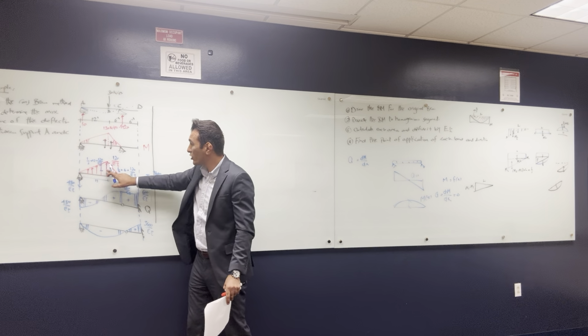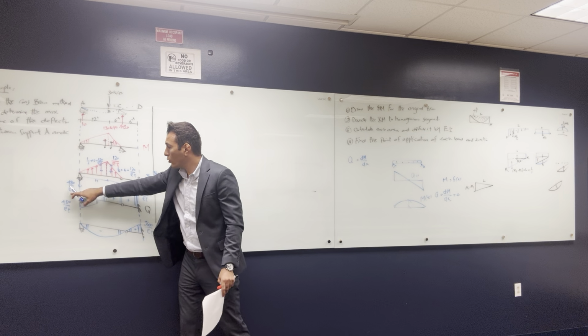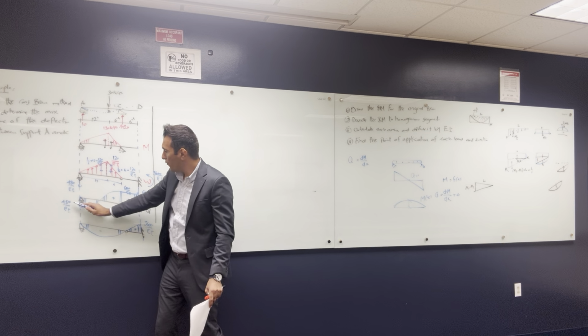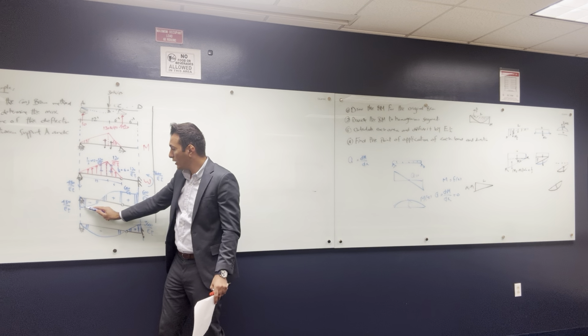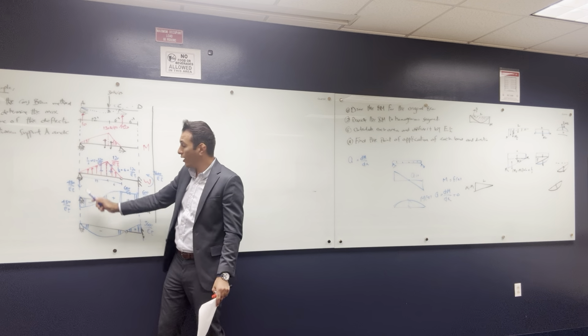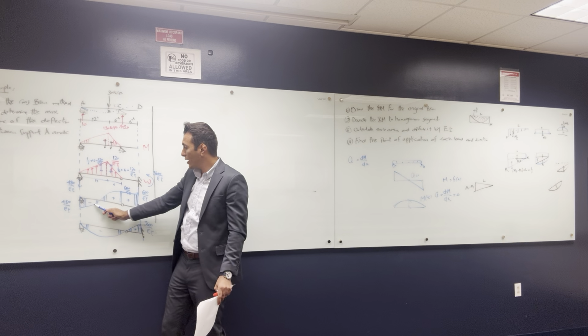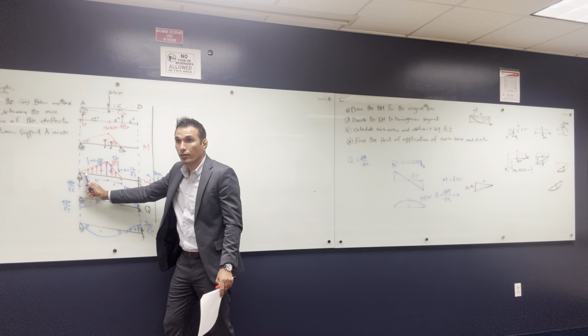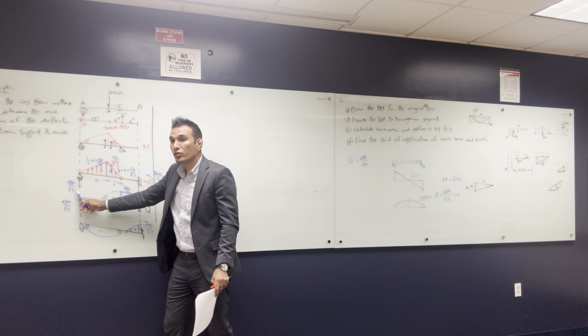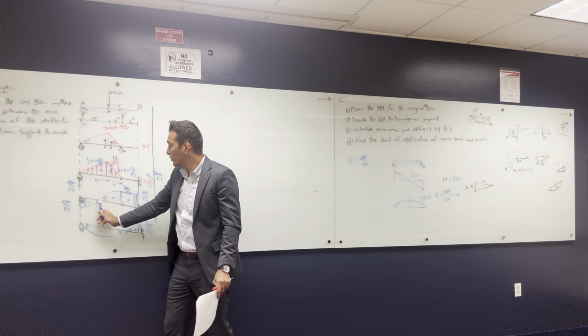I believe maybe this triangle is enough. So you have 480 over EI, and this 480 keeps getting less because the load is going up, and then at some point here it stops at 0. So somewhere in this triangle, this load was able to bring the shear value here to 0.